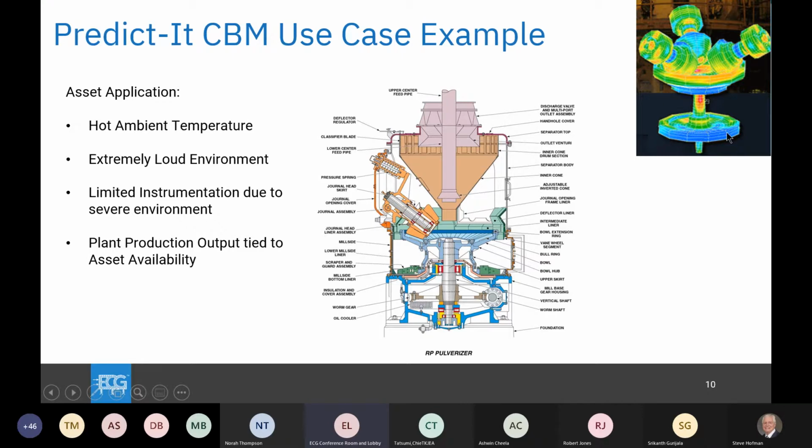And so this is a 3-dimensional model of the 3 rolls crushing the coal on the bowl, and a gearbox drivetrain drives this from an electric motor. Some of these mills are 500 horsepower in size, so this thing's quite large physically. Here's a cross section. You can see 1 roll touching the bowl, and we're going to show you 5 sensors: the motor amps, the 3 rolls deflecting as far as movement, and how much coal's coming in here.